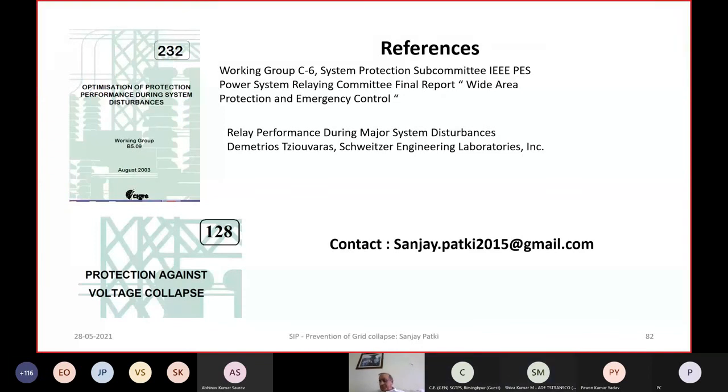Sir, I would like to supplement. Consequent to the 2012 grid disturbance, the Ramakrishna Committee guidelines recommend there should not be any overcurrent protection on EHV transmission, except directional earth fault in case the distance relay fails. Correct. So the question of overcurrent protection itself should not be there for 220 and 400 kV grid connected lines.